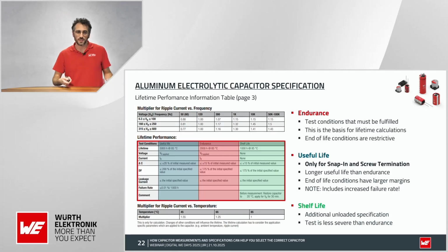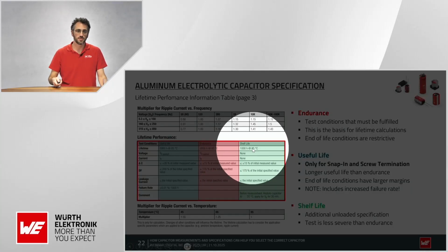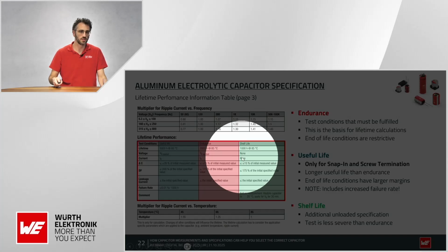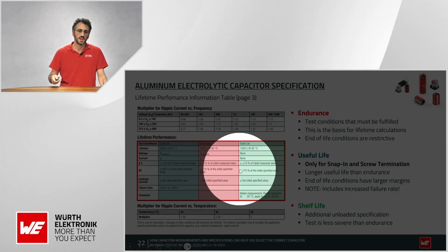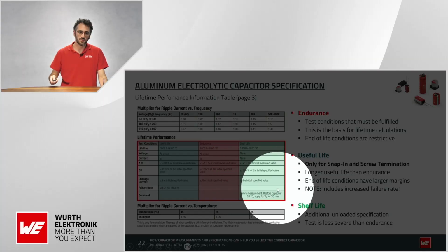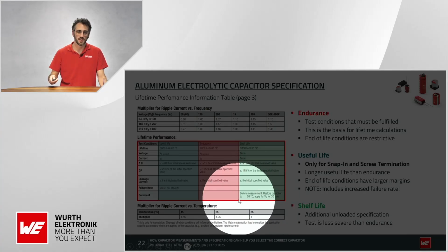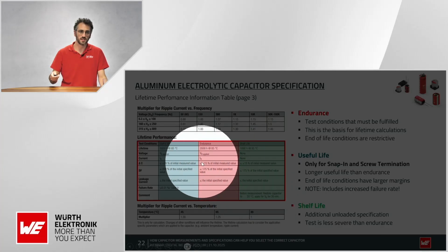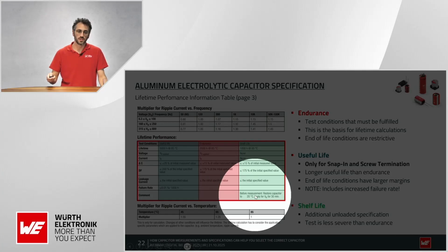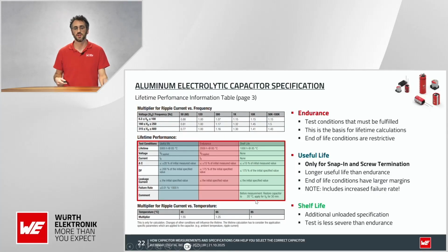Finally, the shelf life is not so important. It's tested only on temperature, not on load. This is why it's called shelf life. And it has the same conditions as the endurance. But of course, this test is always passed because it's always less time and less harsh conditions. But it's important to remember this is, let's say, a delivery aspect. So when you get the components to measure them, you should be able to reform the capacitor, because in this case it is under voltage, but here no. So the conditions are only guaranteed after this restoration of the capacitor, which is done at rated voltage.